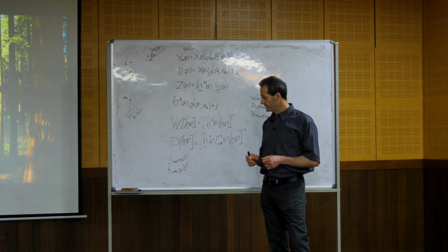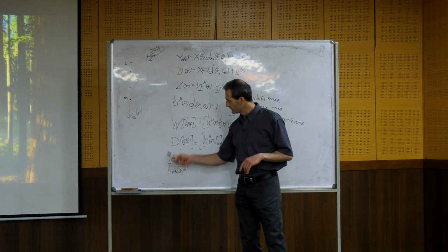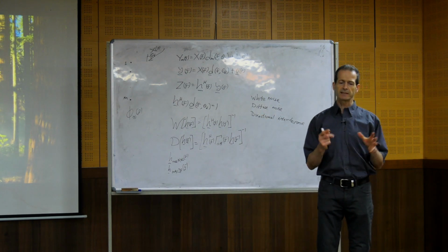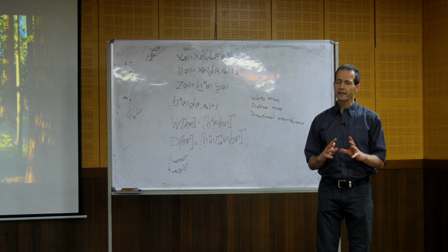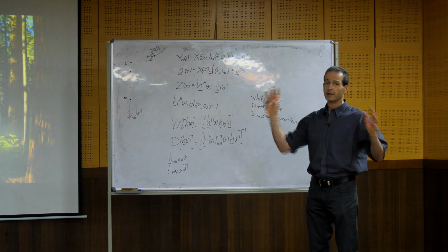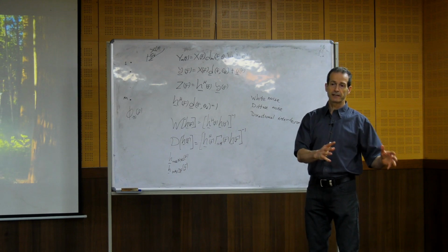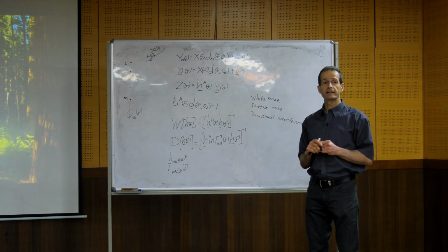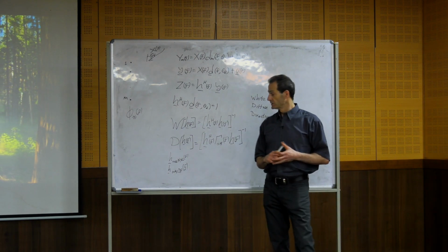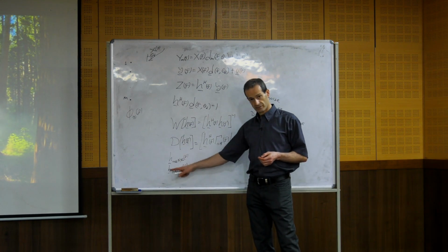Now, on the other hand, if we design a beamformer that will maximize the directivity factor, which means that we design it offline in advance, and we think that this beamformer with the array will be used in an environment with diffuse noise, and then eventually people take it and use it in an environment with white noise, then this beamformer is very sensitive to white noise.